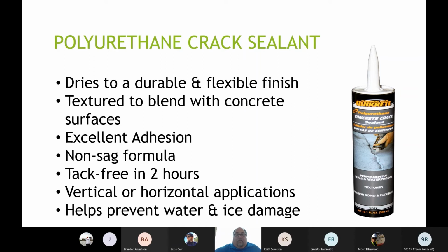So it's very important when your customers ask, I'm just going to repair some hairline cracks. This is great, or the crack seal's there, but just make sure you ask them, hey, is this something you're going to want to go over later with an overlay or something like that? Just so they know in advance that they're going to have to dig it out and they're going to have to grind quite a bit of it out to get the residue off. Otherwise, it will not stick.